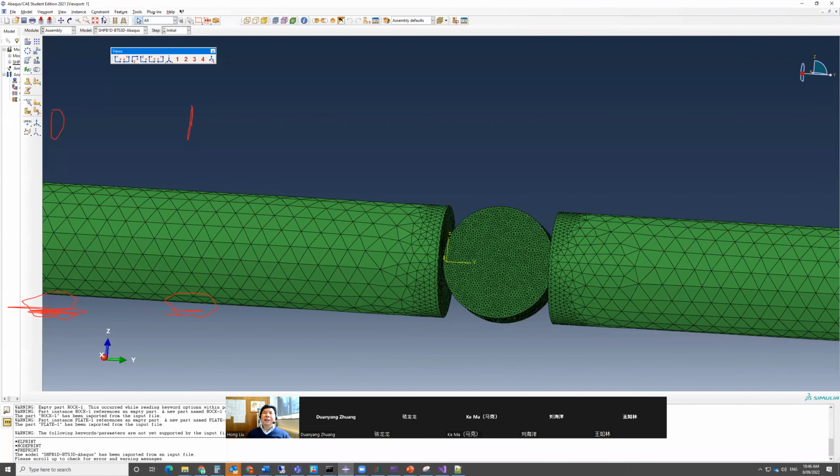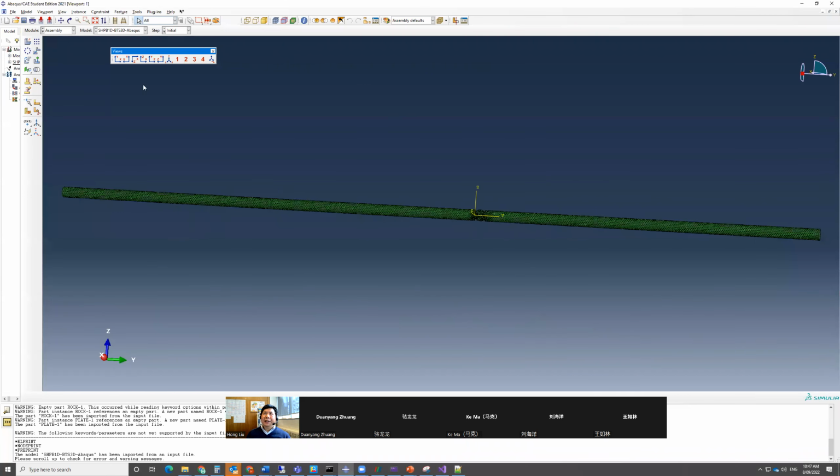Okay, for the boundary condition, we were inputting an impact on this side. When I apply that impact here, I will make this fixed so that I only have this stress wave which is transmitted, and here there is no movement. Then all of the other locations are unnecessary for me to fix anything, so I can make them free.